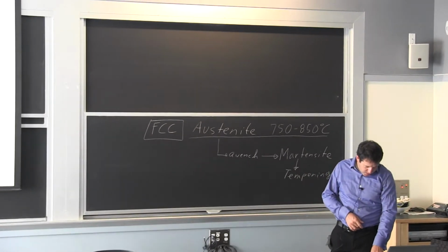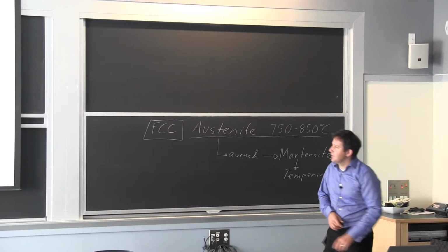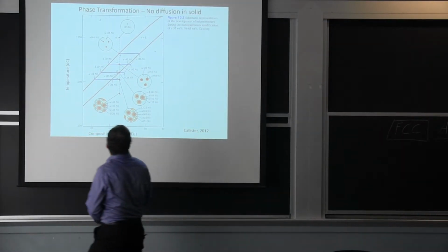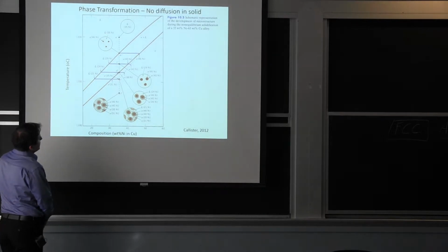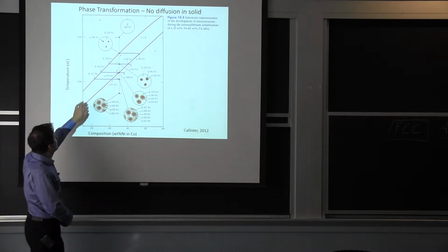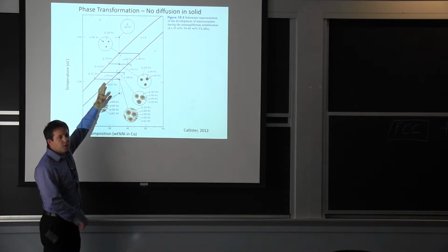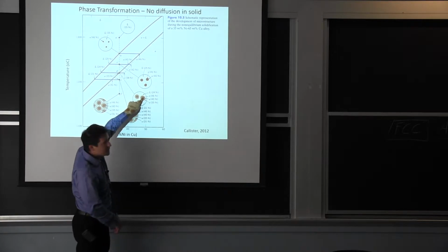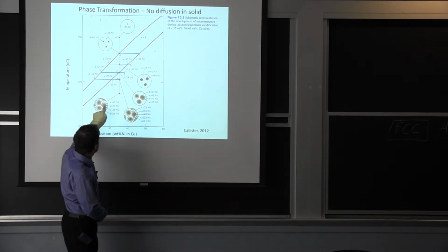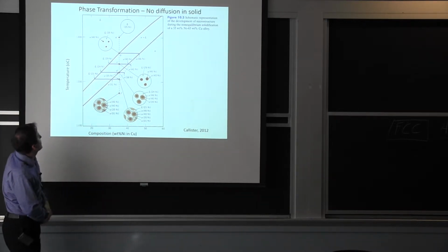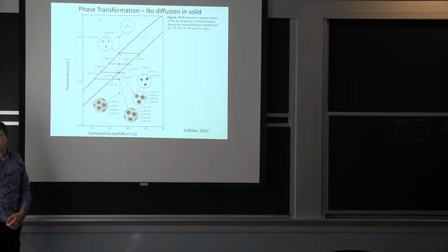So let's take another example where we don't have the diffusion now, and essentially the same diagram. We're still going to solidify, but it's going to take much more time because our concentration in the liquid keeps going down. We're using the nickel at the very beginning here, and we still have the center here at 46%. And then at this lower temperature here, close to 1200, we still have a liquid.